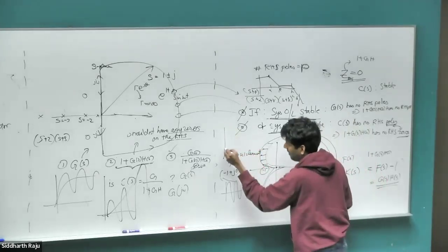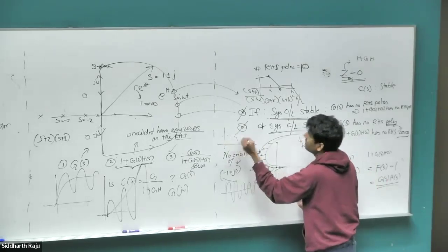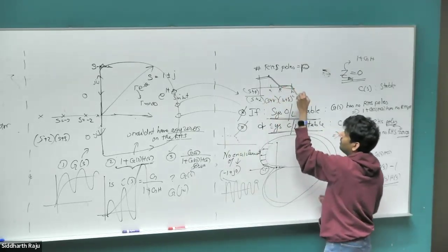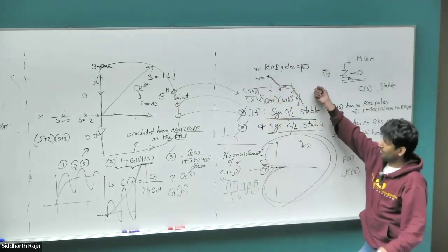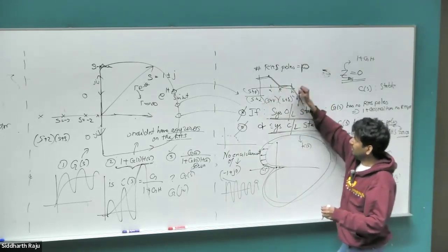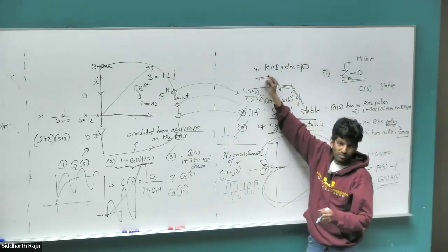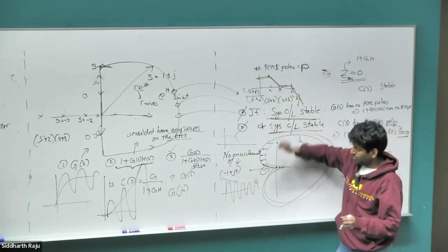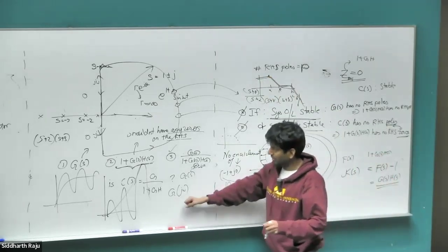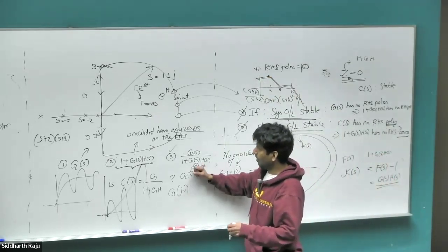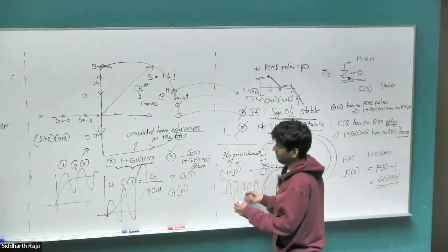And if I plot all the values of the magnitude at different frequencies, that's exactly what I've drawn here. For a complicated system, that's what the Bode plot would look like. At different frequencies, I go and look at what the magnitude was, and that's exactly what I plotted there. Right? So that's the magnitude at steady state. It's basically saying what is G of j omega, ignoring all the alpha components, which is the transient exponential component.